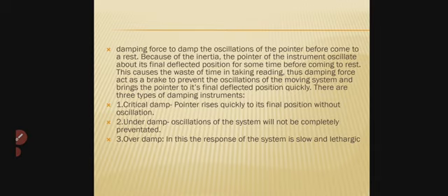Damping torque is necessary to bring the pointer to rest quickly. If there is no damping torque, then the pointer will keep moving to and fro about its final deflection position for some time before coming to rest, due to the inertia of the moving system.